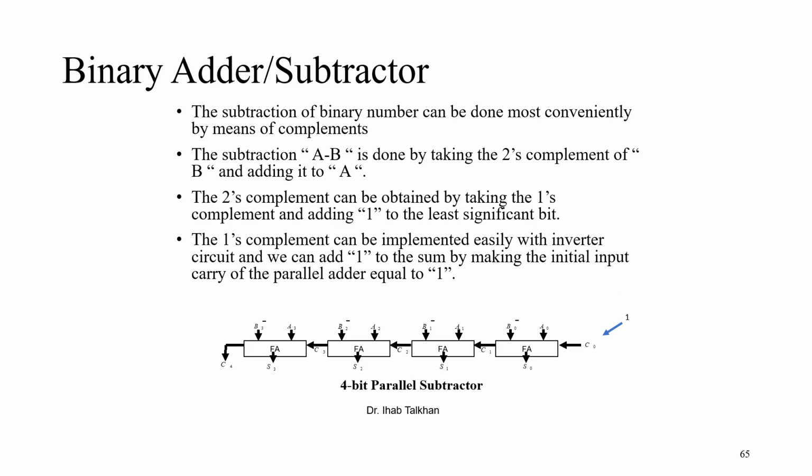In this slide, we are going to play with the hardware we ended up with in the previous slide. We are going to exchange the full addition into full subtraction based on the complement of a number. Remember the complement of a number, we have two's complement and one's complement, and we use them in order to get rid of the negative sign. So the negative number can be exchanged by taking the two's complement, and then adding it to the positive number. We end up with a subtractor. So this is the way we're going to do it here.